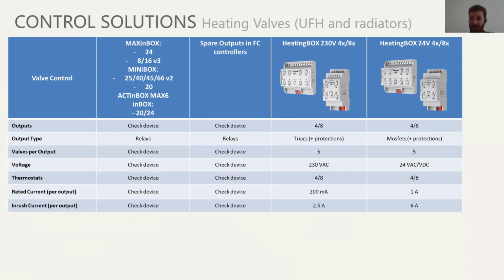In a KNX relay, you will always have, first of all, that click, click, click, click sound of the relay actually closing the circuit and opening the circuit. Other is that the relay life is limited. In our devices it's usually rated for 10,000 switches or 10,000 cycles, opening and closing.